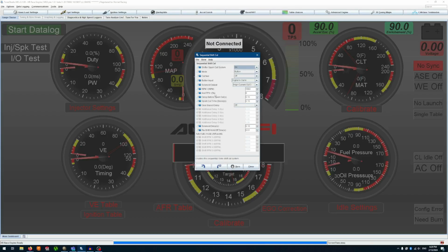So basically it makes it so that you can shift all the time, which if you think about it sort of makes sense, because if you're stopped, then your TPS is probably 0, but if you're idling, it's above 0, so you can still upshift into second gear if you really wanted to, but you would just downshift into first.